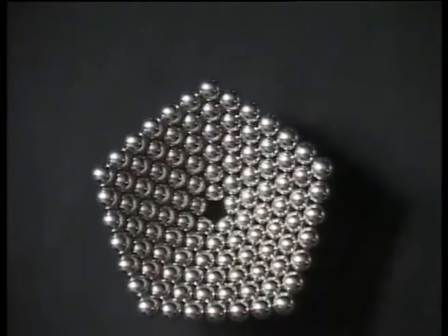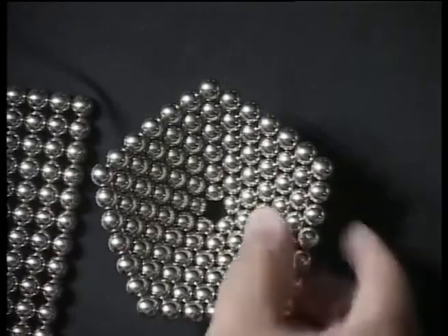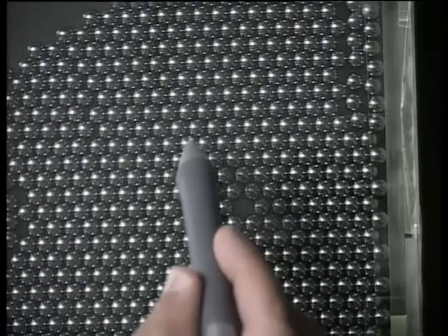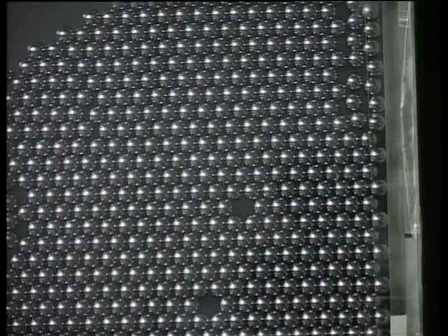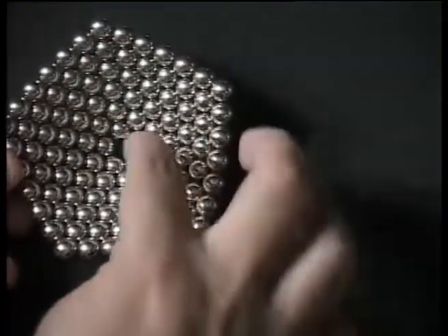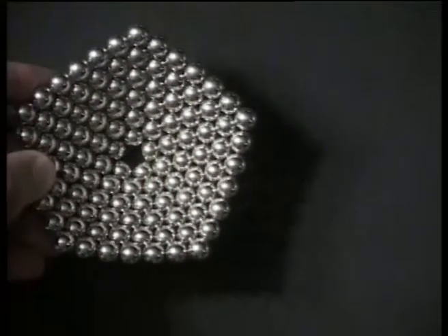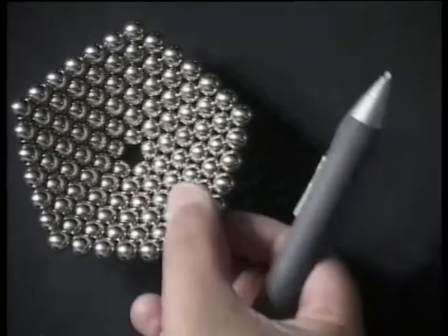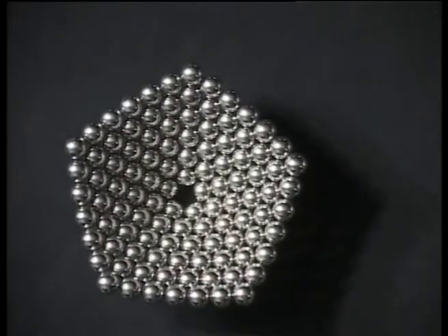The normal coordination, as you can see from this model on the left hand side, is in a preferred orientation, which I will bring back into focus. The normal coordination is 6. That means around any central sphere there are 6 spheres. This is what is preferred, and this I would call the normal crystalline array in 2 dimensions. But in this case, the normal coordination has been broken, and you can see there is a pentagon in the middle, and this is a defect associated with rotational symmetry of this crystal, and this I can call a disclination.